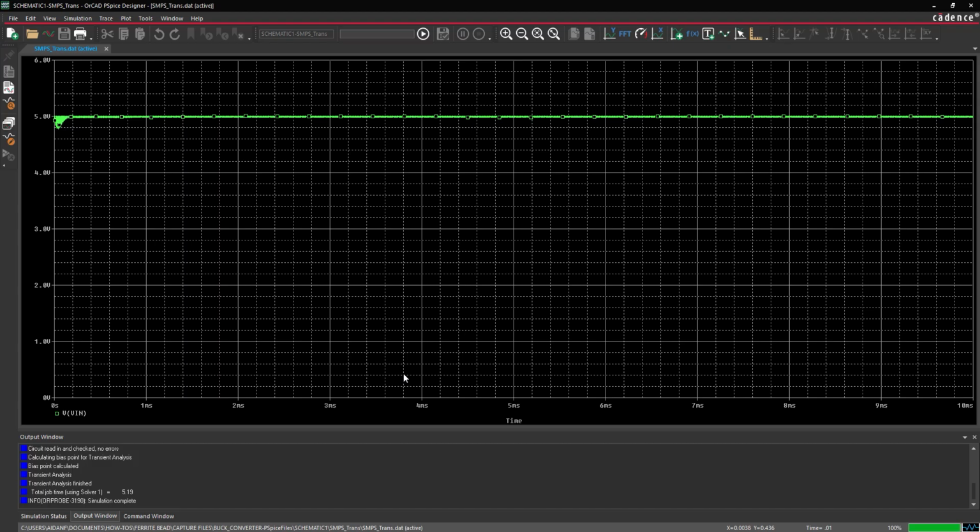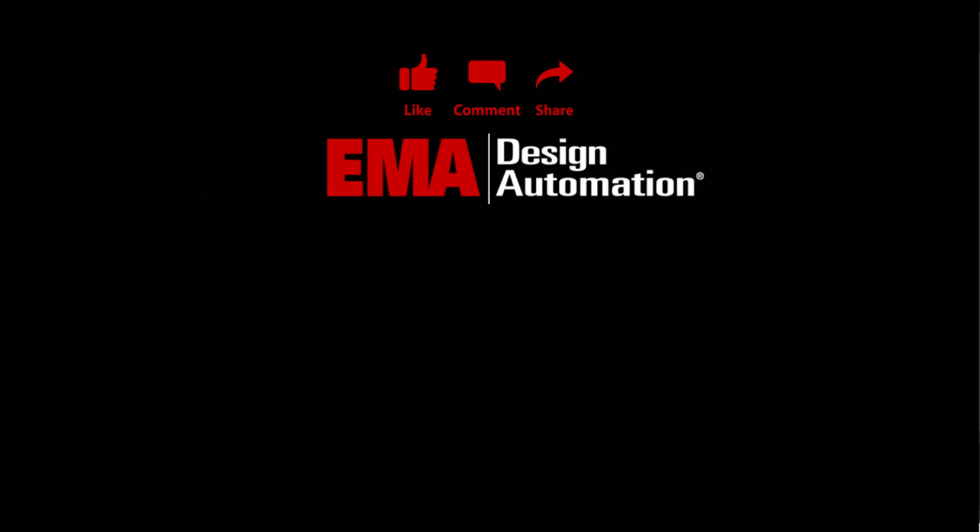Now you can view the plotted results. The noise has been filtered out by the Ferrite bead and the SMPS input holds steady around 5 volts. Quickly create a Ferrite bead spice model based on datasheet parameters to model accurate circuit behavior and ensure proper noise isolation with PSpice.